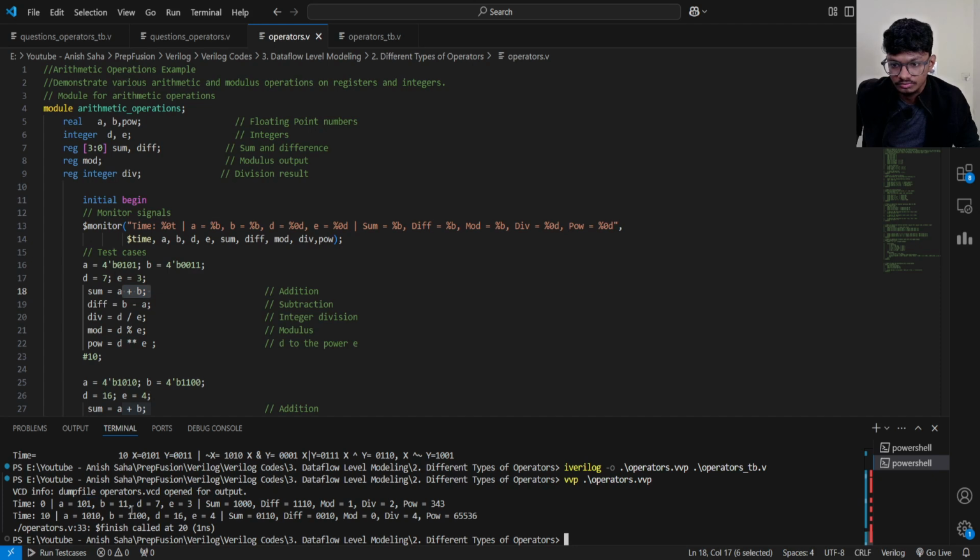So this one becomes 0 here. Then I have another 1, and this one is already there, so again it will become 0, and then again I have another 1 and I have 0, so it will become 1. Sorry, there were 2 ones, right? So again I have a carry of 1, so 1 1 again becomes 0. So ultimately I have a carry of 1, so I have a 1 here.